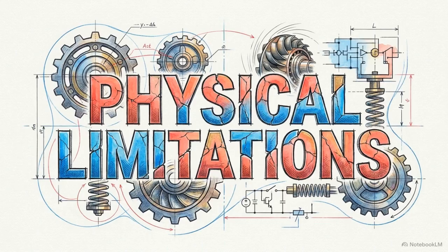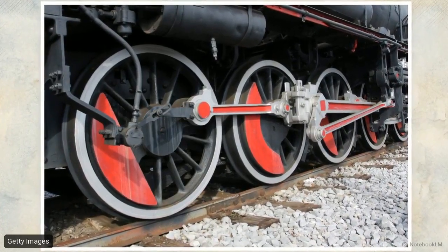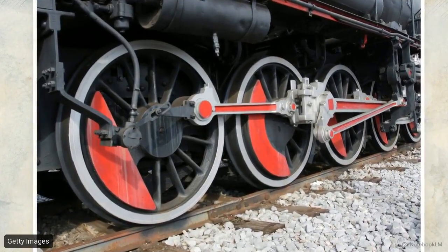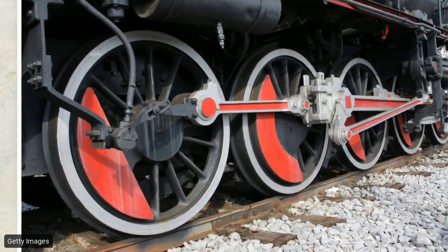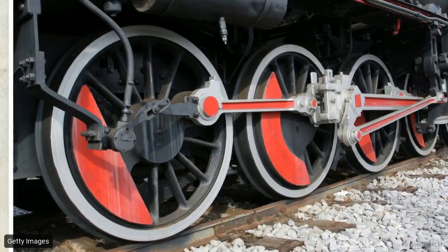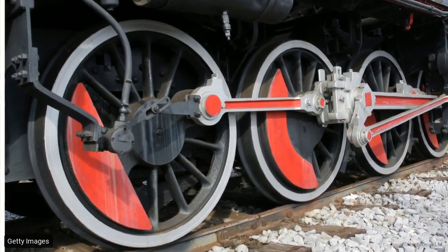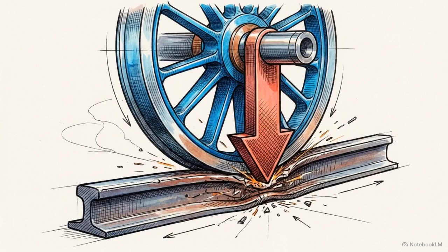In reciprocating engines, completely neutralizing a force is a geometric impossibility. You can only relocate it. Look closely at this image of locomotive driving wheels. You can see how engineers physically implement these flawed rotating counterweights, cast directly into the red sections of the steel. The first destructive symptom of that relocated vertical force is known as hammer blow.